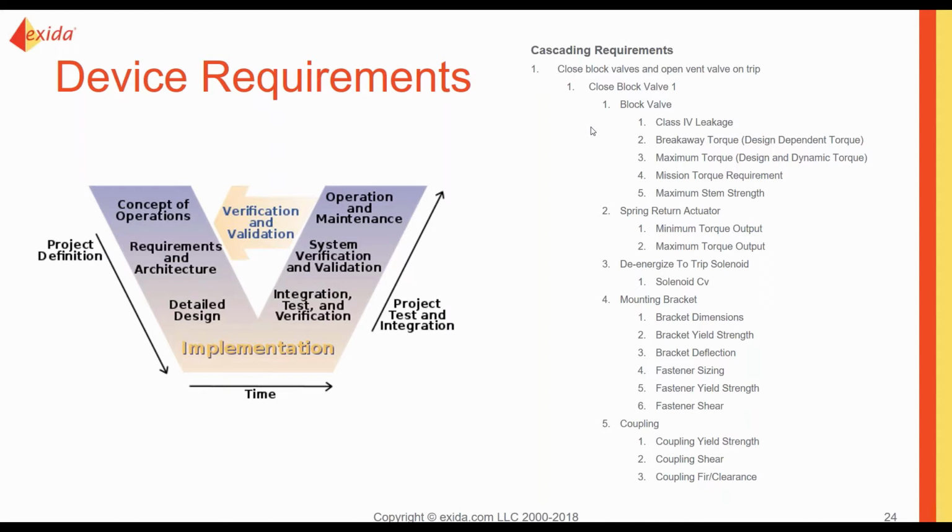Well, for the block valve, we're going to have leakage requirements. Then we're going to have things such as torque requirements. We'll touch on this a little bit today, but we'll have another webinar just on this subject. With torque, we've got breakaway torque and maximum torque. Those are 2 things that are pretty well understood today. However, we've seen cases where brand new valves have been installed, and within the first month they've sheared the stem off. And these are safety rated valves in safety applications.